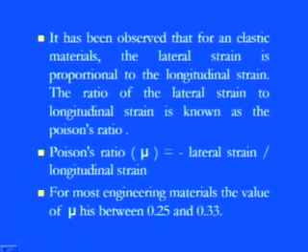So, the ratio of the lateral strain divided by the longitudinal strain will give you a new term. Again, you see it is a strain by strain, so it is a non-dimensional parameter; no value, no unit, no dimension is there. But it will give you a direct relation: once you apply a compressive load or extension, you see how the changes are there.